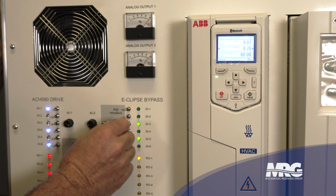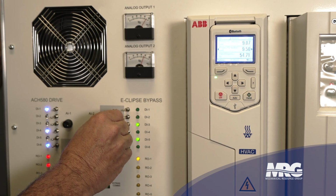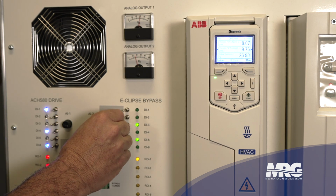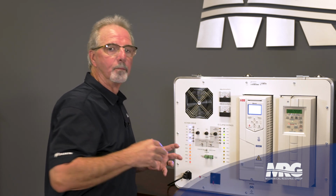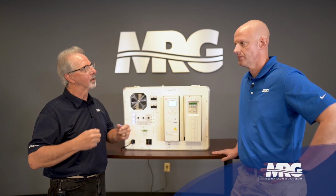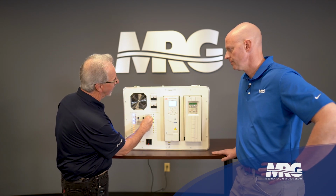As I approach back, now I'm pressurizing the stairwell. As I approach back and get closer to my 9.07, my fan begins to slow down. It'll speed up, it'll slow down. And what this is kind of doing is mimicking what happens when you open the door in a stairwell. Because as you open a door, we lose pressure, and so the fan has to speed up to keep the same pressure in there. So that's what we're doing with this right here.